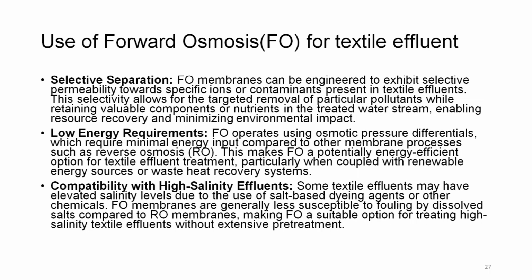Compatibility with high salinity effluent. Some textile effluent may have elevated salinity levels due to the use of salt based dyeing agents or other chemicals. FO membranes are generally less susceptible to fouling by dissolved salts compared to RO membranes, making FO a suitable option compatible with high salinity effluent.